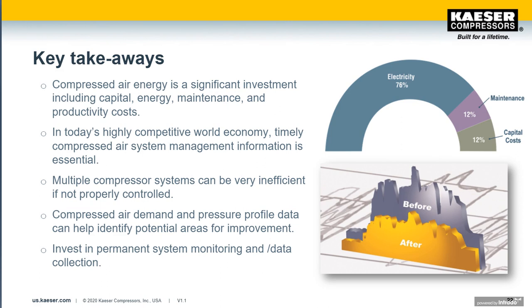In order to understand your system, you need to understand your demand profile, your flow profile, like we looked at a little bit ago, as well as your pressure profile. And again, we showed one of those too. The best way to get this information is to invest in system monitoring and data collection. Better yet, a master controller that can operate your equipment efficiently as well as collect historical data.